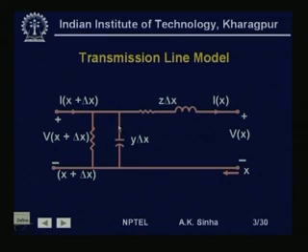Similarly, we will have a capacitance to ground for the line, which will be y, and for delta x of the line, this shunt admittance is going to be y into delta x. That is, capacitance will provide us an admittance j omega c, which will be equal to y, and that will be per unit length of the line, multiplying it by delta x, the length of the line, we get y delta x. Here I had also shown a conductance path for the line.